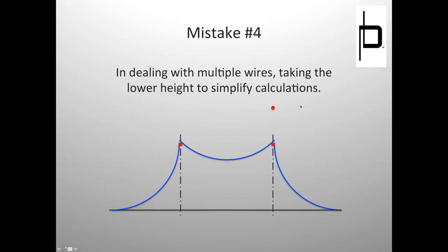I guess if your client wanted more height for their device, you may want to keep the higher wire as well, so that there's more space of protection. I would never recommend to my client to lower the wire. What I'm saying is, just as I'm modeling it, for ease of calculation, it's easier to assume these are the same height. But if my client has a wire here, I'd probably say keep that wire there. I'd have to look at this side strike coming in and make sure it doesn't roll underneath.